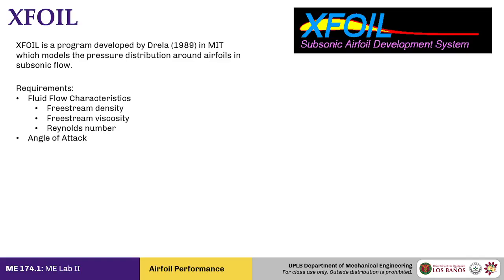Now for the angle of attack, this is quite important. You have to specify the range of the angle of attack that you want to examine. So for example, I want to examine airflow from 0 to 15 degrees angle of attack. You have to say that, and then you have to say what increments. Do I want my increments to be fine, like 0.1 degrees, 0.2, 0.3, or is it okay if I just go default, like 1 degree, so 0, 1, 2, 3.